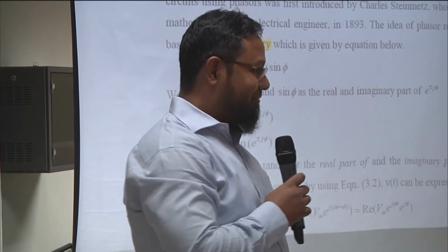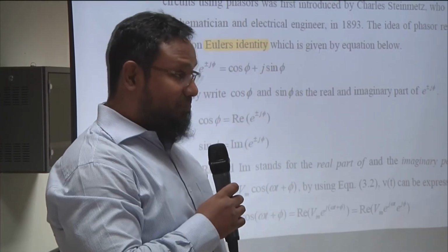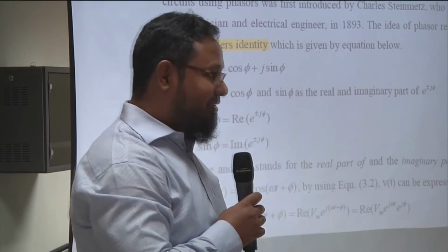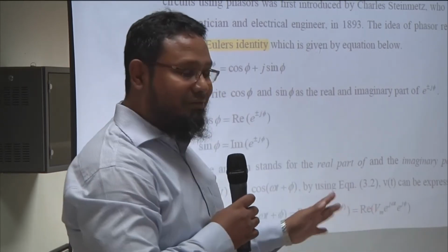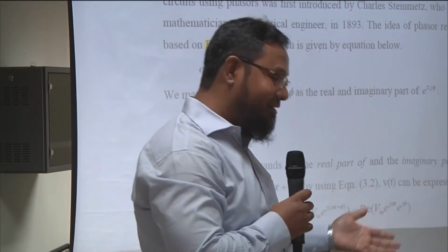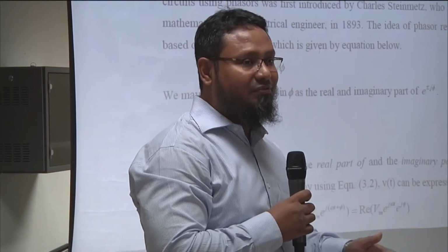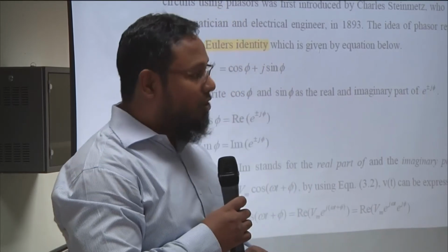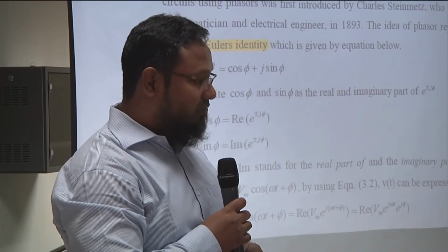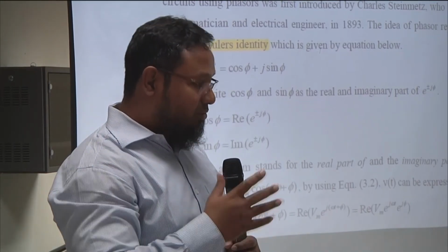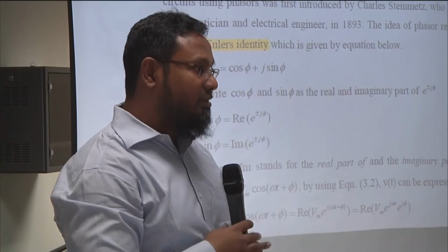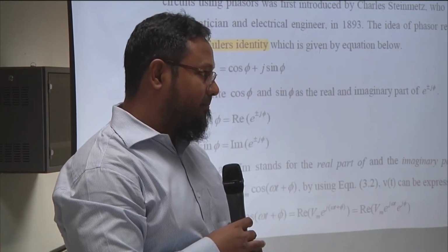That is the standard. But believe me, if you represent everything as a function of sine, the calculation will be accurate. There is no problem with that. But the standard that I realized later is to convert everything to a function of cos and take the angle of that. Whatever phase you have as a function of cos should be the angle of your phasor. Okay?